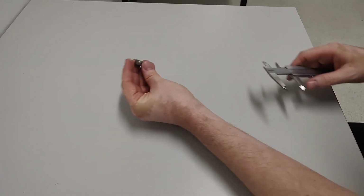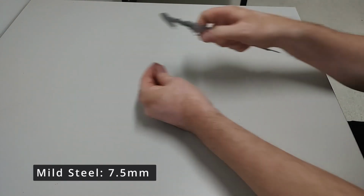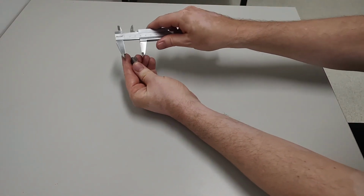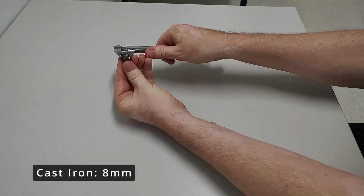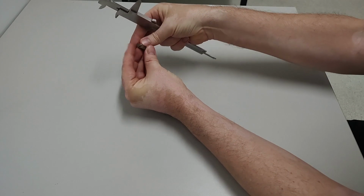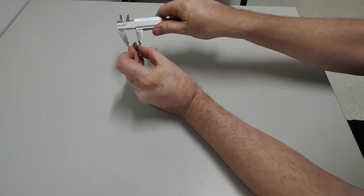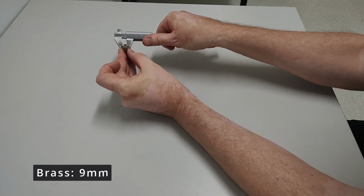We will now measure the final length of the compressed samples with vernier calipers. The mild steel measures at 7.5 millimeters. The cast iron measures at 8 millimeters. And the brass sample measures at 9 millimeters in length.